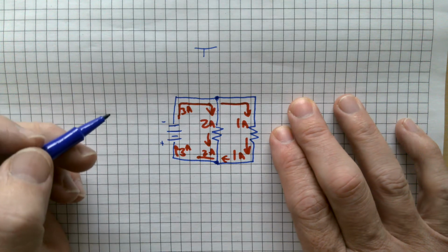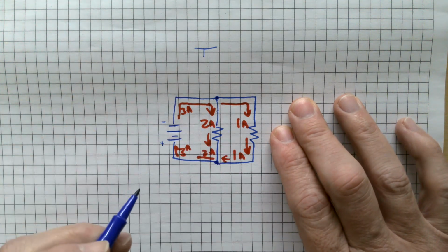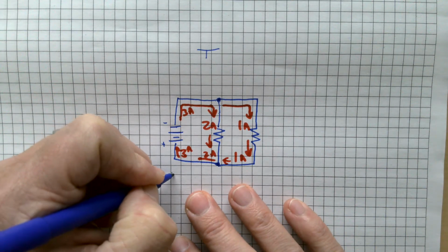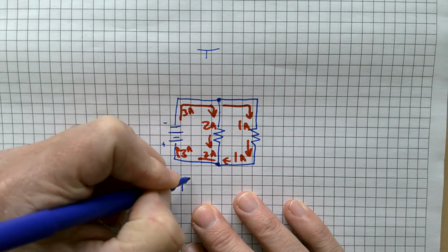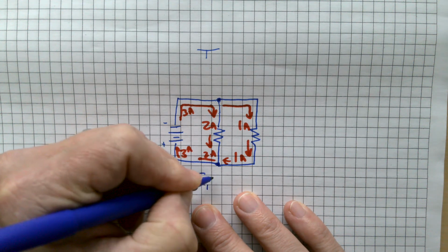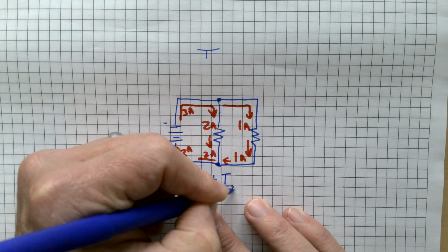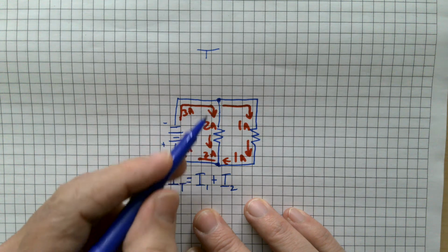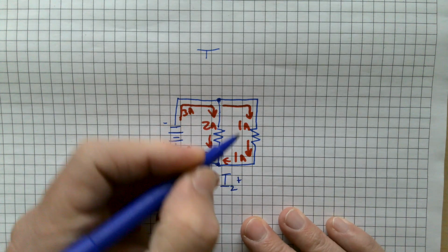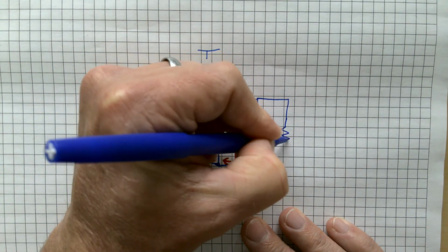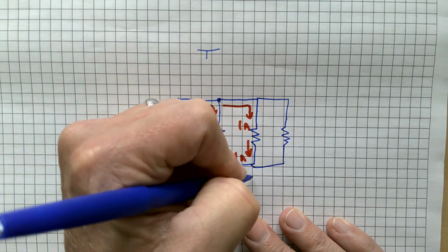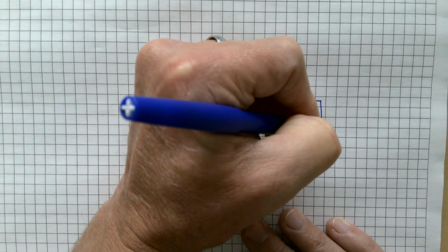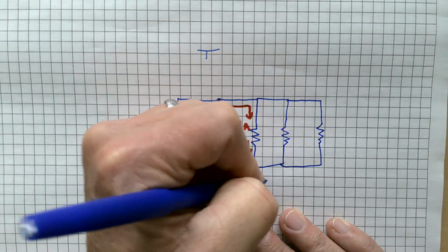So as we work out the math in these things, I want you to remember that current does add up. So we have a formula now called I total equals I1 plus I2. And this is current at the resistor, even though you can measure it anywhere in that branch. If you had more, so if you had a third resistor out here, this formula would extend. See that? If you had another one, and it just depends on how many resistors you have in your circuit.